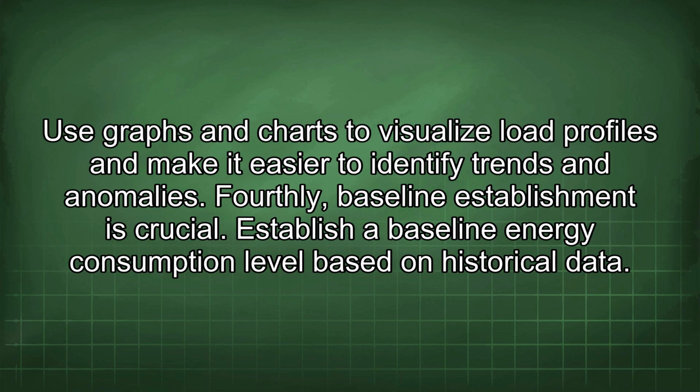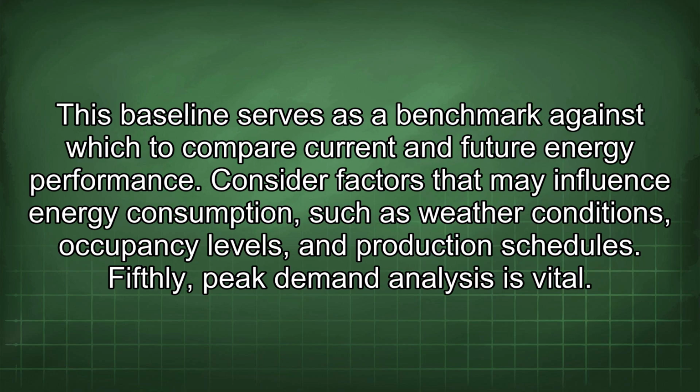Fourthly, baseline establishment is crucial. Establish a baseline energy consumption level based on historical data. This baseline serves as a benchmark against which to compare current and future energy performance. Consider factors that may influence energy consumption, such as weather conditions, occupancy levels, and production schedules.